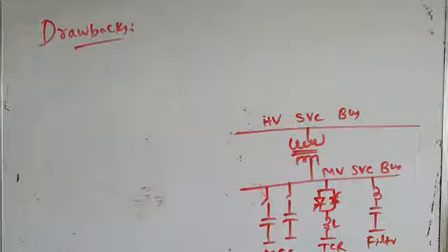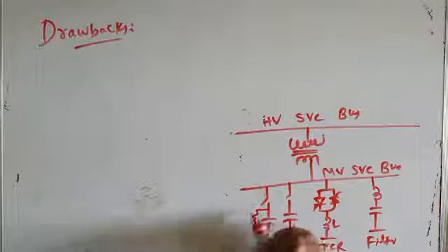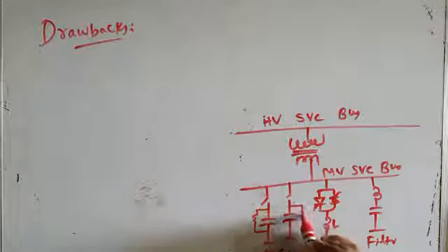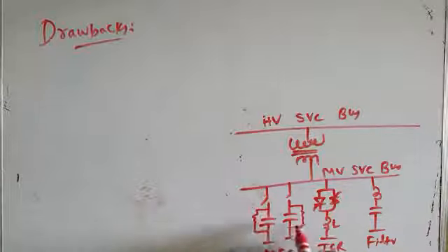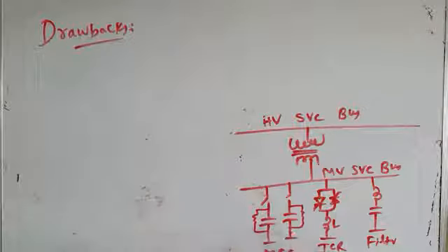Okay, now in order to remove that trapped charge, resistors which are inbuilt within the capacitor banks, these parallel resistors, discharging resistors, are generally connected, and the capacitor banks, when they are opened, discharge through these resistors, but the discharge time is very, very high.